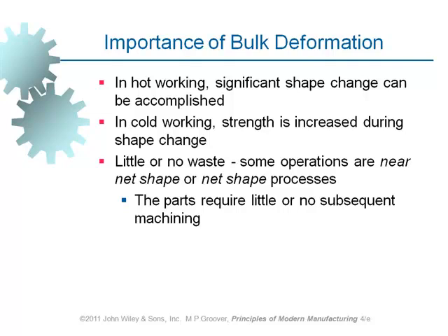When new grains are nucleated and they grow, a stress-free grain is produced. A stress-free grain is produced which has got the properties of the original material, which is not yet subjected to any deformation. And we change the shape again. And after some time, again, new grains are formed, so we can continue and continue and continue processing of the material without failure.